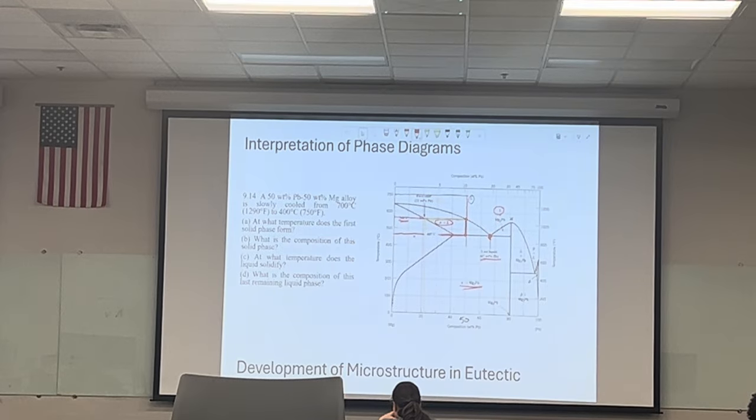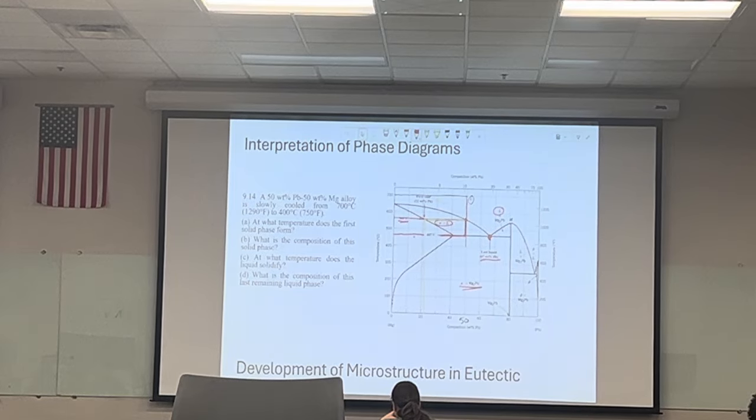Above it you have basically the liquidus. So it goes straight from liquidus to the solidified part right at this point, at 465 degrees Celsius. It doesn't go through the alpha plus L phase, it just goes straight from liquidus to the alpha plus magnesium-lead.